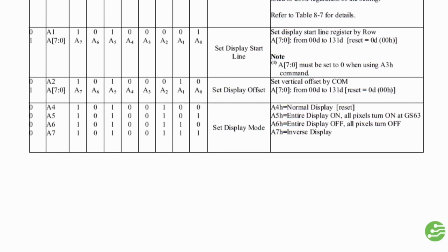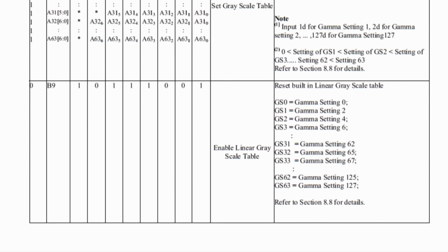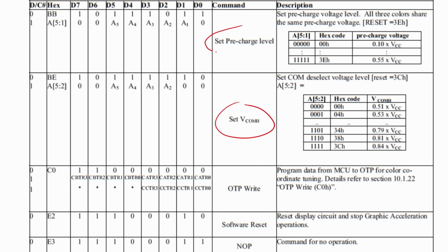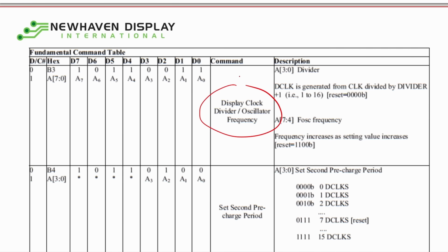The other feature of the driver chip that you need to be familiar with are the configuration registers. Driver chips are designed for a certain type and a maximum size of display, but can be used in displays with differing properties. Because of this, there are registers to set things like voltage levels, charging time, clocking options, and so forth.